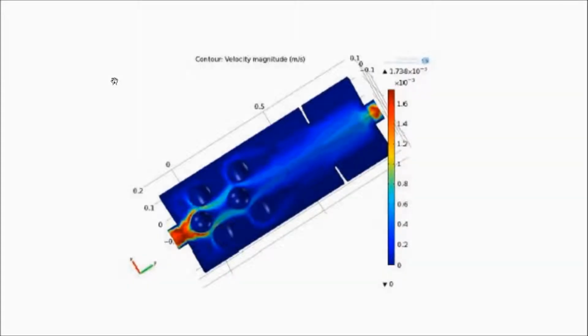Figure 7 shows the velocity profile. The highest velocity is located at the red region, which is at the inlet and the outlet. This is due to the small surface area creating high velocity when water passes through it. The middle has bright blue, which is at the midsection, as it flows through the narrow section, creating a low pressure. The flow area affects the velocity: the smaller the flow area, the higher the velocity passing through the heat exchanger.